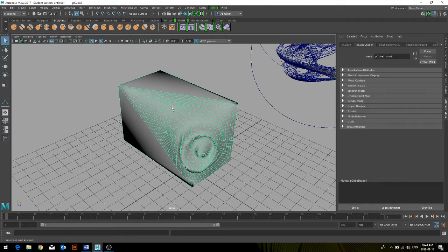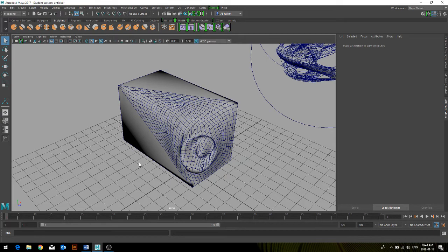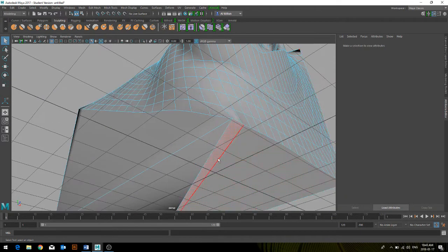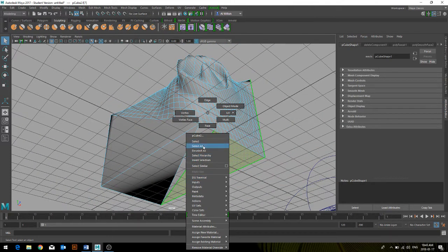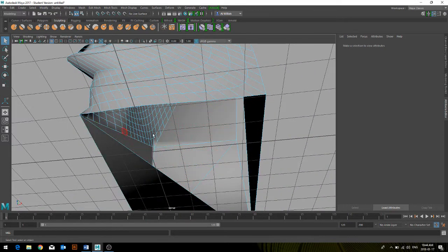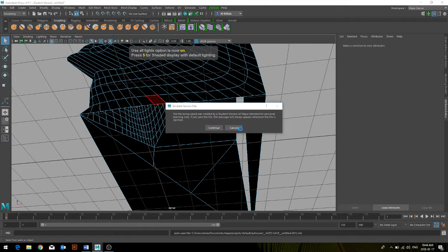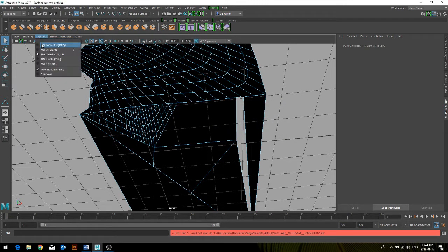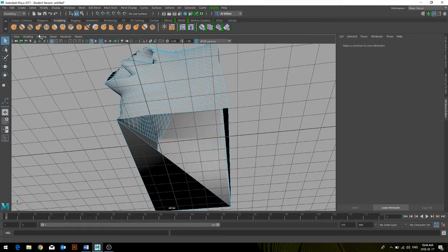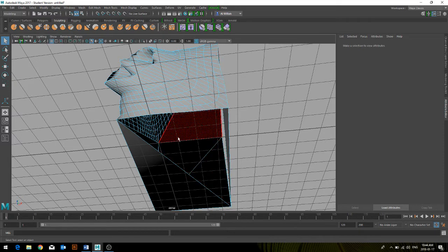Another interesting one is under the lighting tab. You can see two-sided lighting, which is really useful if you are in a situation similar to what Mattiar had before, where you select a face and it allows you to see a shaded view of the inside, whereas before, with the default lighting, it's quite dark and hard to move around in. The two-sided lighting usually highlights everything inside.